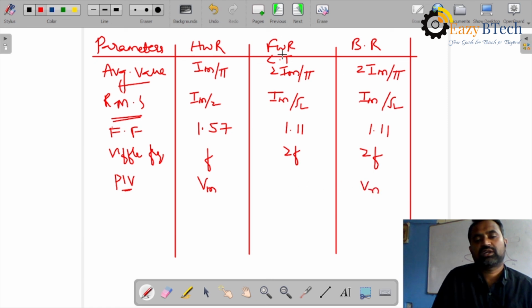For the bridge rectifier, and for the center tapped, two diodes are there, with two different voltages. One during the positive half cycle the upper is positive, and during the negative half, because in a center tapped transformer the secondary voltage is equally divided. During a positive half cycle, D2 is reverse biased, and during the negative half cycle, D1 is reverse biased. That is why the peak inverse voltage is 2 times. That is why we write 2 Vm, peak inverse voltage of center tap rectifier.